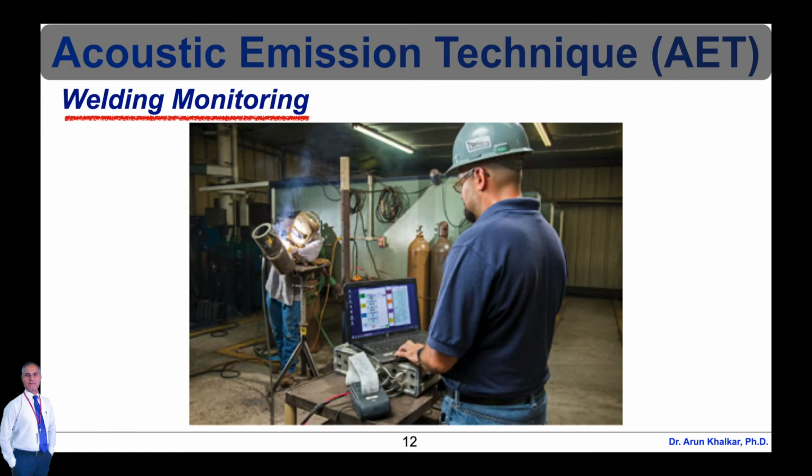Using stainless steel welds with known inclusions and accelerometers for detection purposes and background noise monitoring, it was found by W.D. Jolly in 1969 that low-level signals and more sizable bursts were related to the growth of microfissures and larger cracks respectively. A standard practice of AE monitoring of continuous welding is shown in this picture.